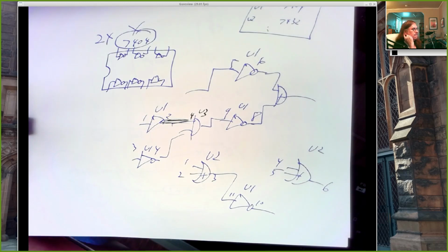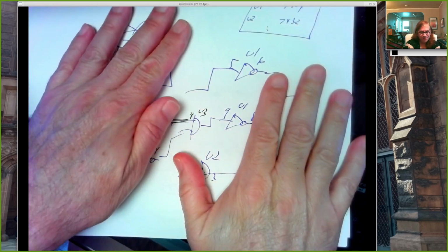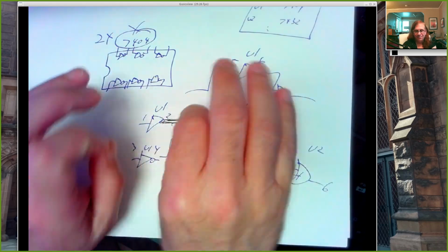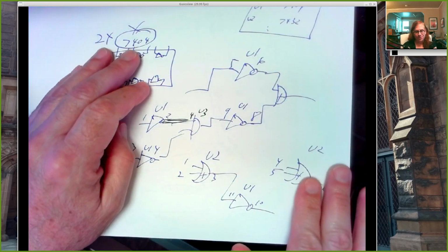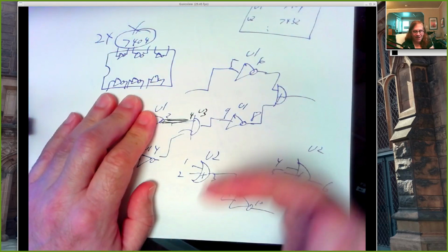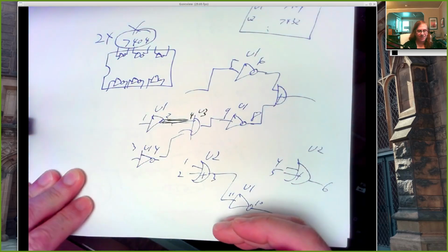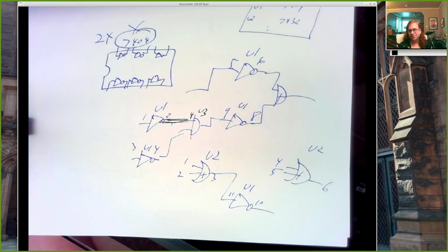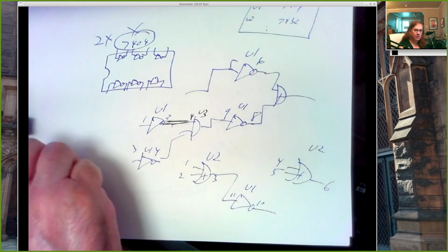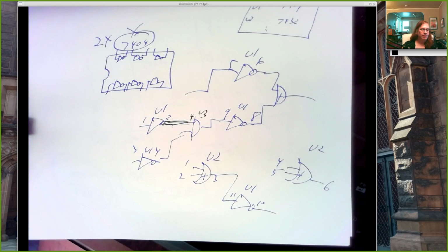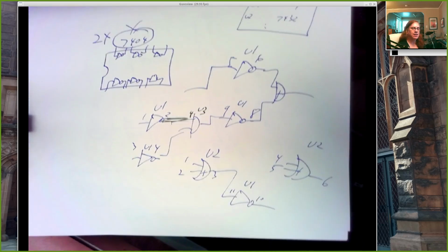And you can do it in parts, right? So we said you can do each lane independently, so you can make your full schematic for one lane, and then build that in Tinkercad and make sure it works. But then go back and add in the other 2 lanes on your schematic, and go back and then add that circuitry. So you can still be building in Tinkercad while you're doing this, but it's probably cleanest if this always comes before putting the parts into the proto board, whether that's in Tinkercad or in the laboratory.